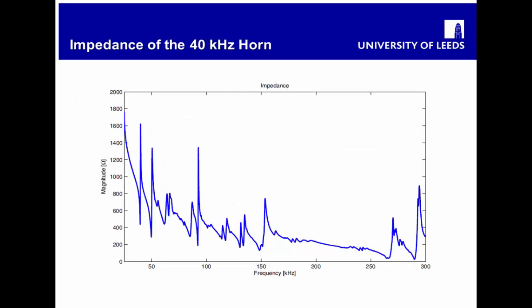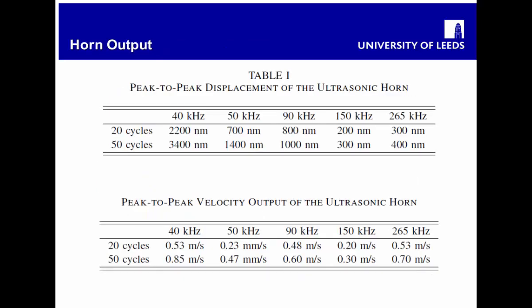Yeah, it's really good. It gives lots of force. But 40 kilohertz is too low for any biomedical ultrasound application. So I measured the impedance of this horn. There are other resonance peaks as well. So I focused on the other ones and did measure the displacement and velocity too. And these are the results that I get.